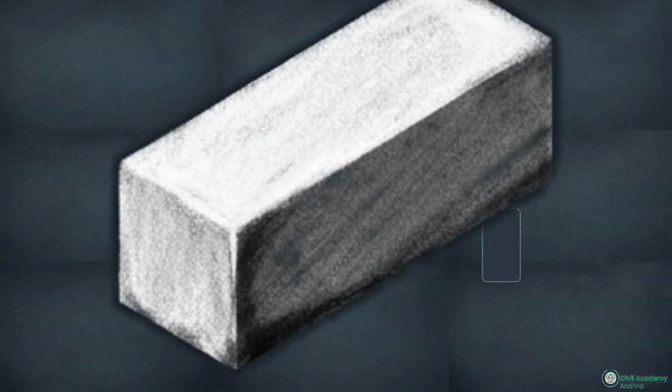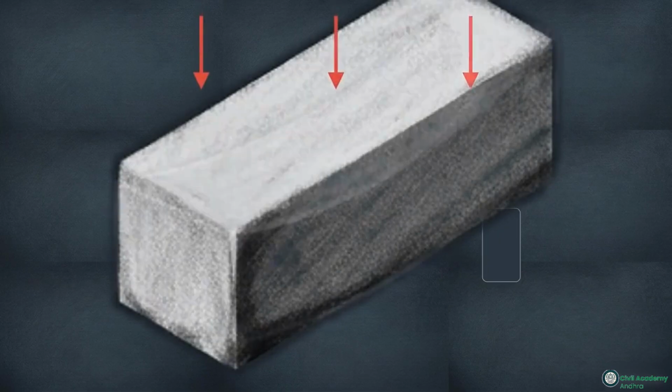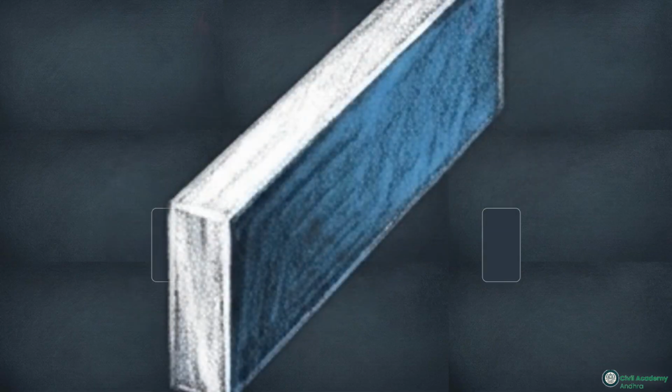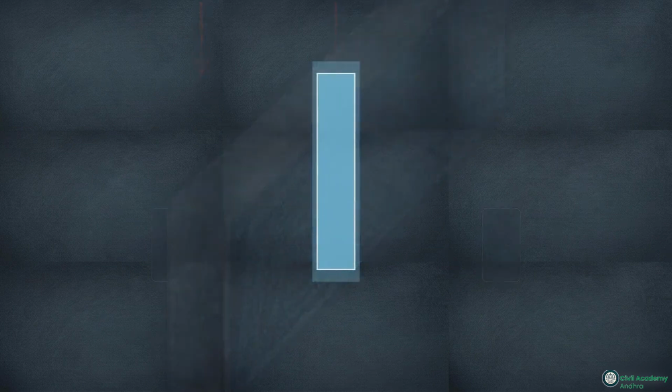This 3D illustration shows a simple rectangular beam reacting to force. When we push down on its wide, flat face, it bows heavily. But if the beam rotates 90 degrees, applying the exact same force to the thin edge produces zero deflection. The material hasn't changed, the mass hasn't changed. The only difference is how the area is arranged against the bending force.